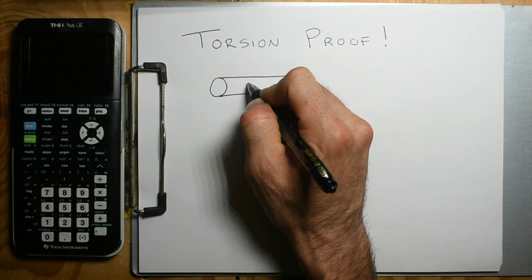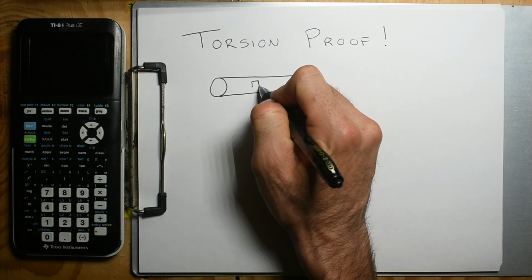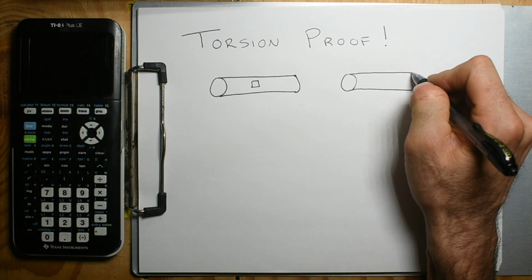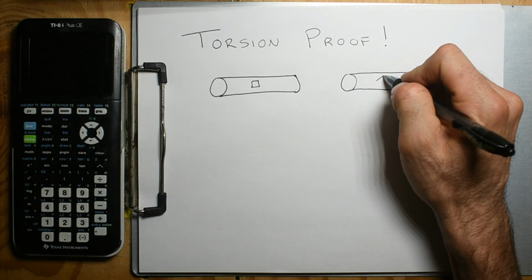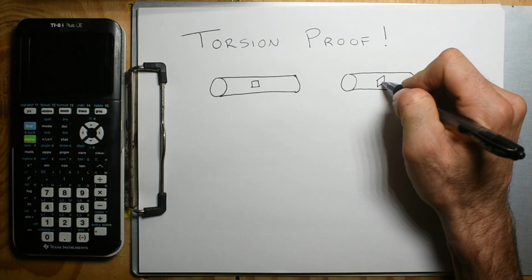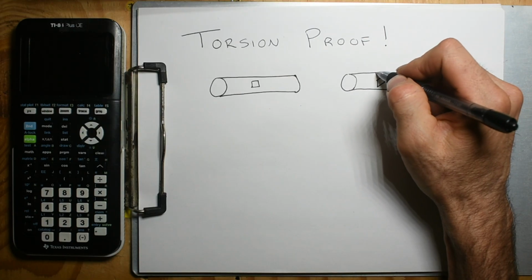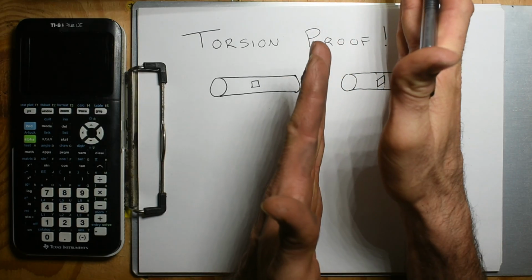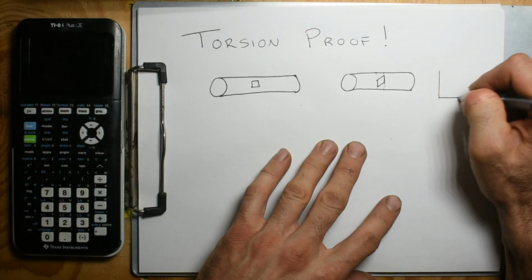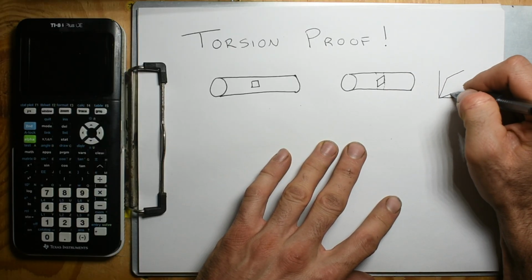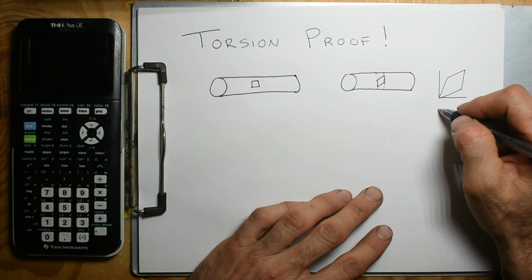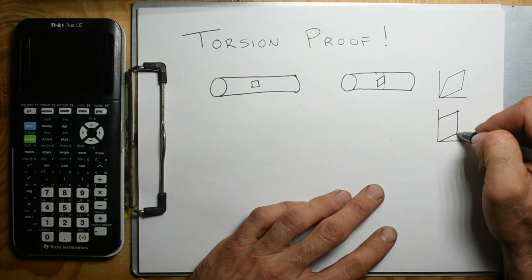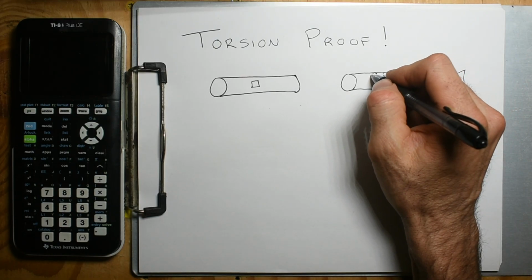So when it comes to torsion, we're going to be shearing. So that little square, after we torque it, is going to turn into a diamond. And so what direction? I just like to draw the diamond this way. So there you go. The other aspect of this diamond that should be relatable is that the diamond just goes this way. You know what I mean? It doesn't go in the classic oblique diamond shape like that. We're talking just a diamond shape, it used to be a square and now it's like that. So we have vertical walls. That's the first important part.